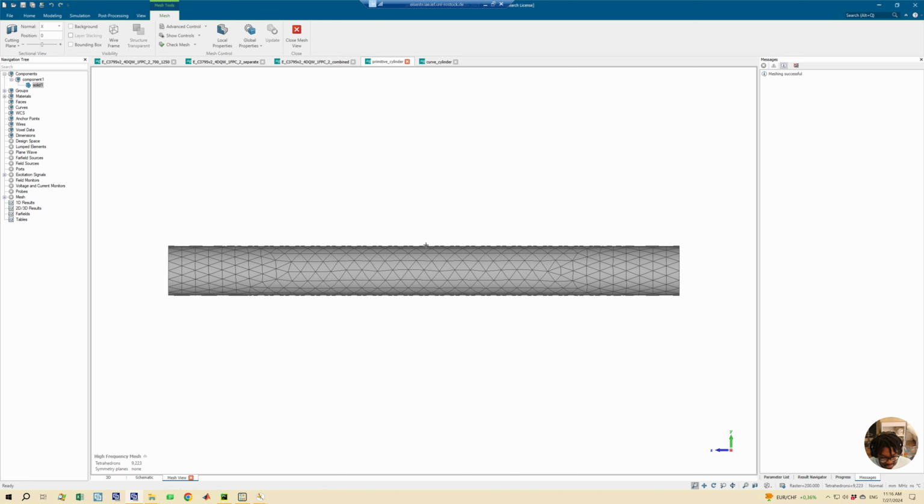But then if I click my spacebar to get everything all nicely centered, and then I also click my spacebar for this, you see, now you can see the difference. You can see some difference in the mesh generated, although it doesn't look that drastic comparing with the eye. So you see the difference around this region. So pay attention to this region, then you see the mesh change, and also around this region. So the answer is yes, it does change the nature of the mesh generated for a tetrahedral mesh.